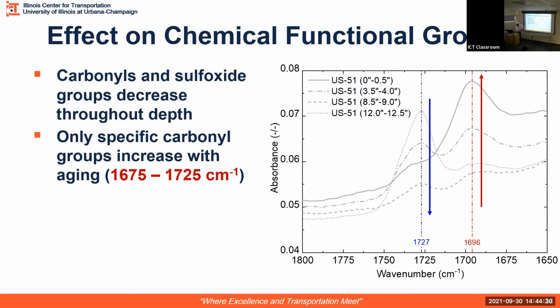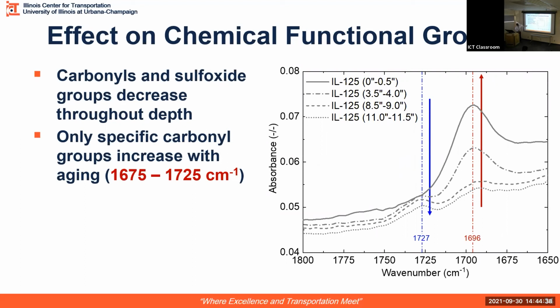So it should be taken care of what carbonyl functionality you are considering when you are considering aging. Similarly here, there's not much increase because it didn't have that oil kind of properties, but you do see an increase in carbonyl specifically in this wave number region. So again, you should be careful with what carbonyl index you go for if you want to assess.